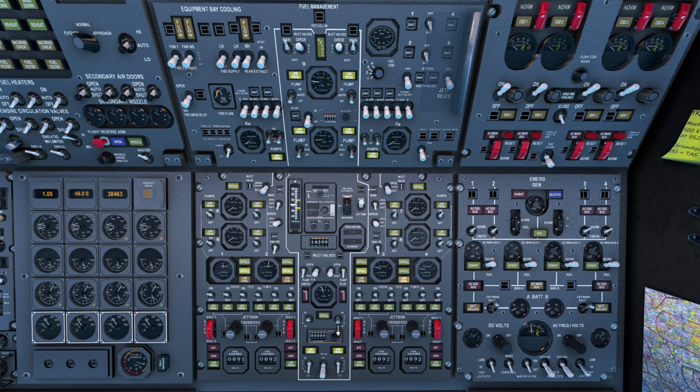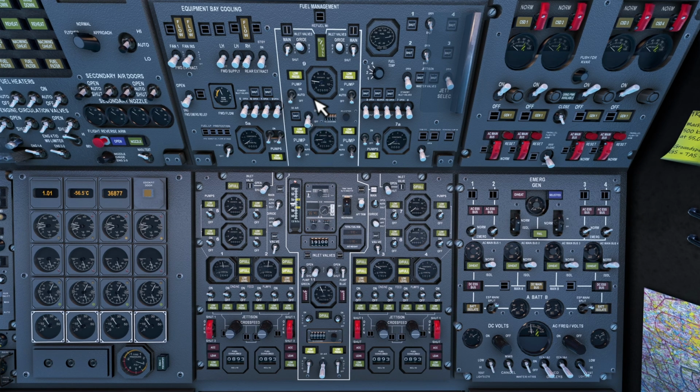I'm going to stop the pumps at tank 11. Close the inlet valves, open another route into that right system. I'm going to use the inlet valve for tank 7, and if I turn the pumps on now, it's going to pump fuel to the right side. It's also going to put the CG a little bit to the front, but the situation here is more important. You see fuel is coming up. I'm going to fill these tanks a little bit and then continue pumping to the back.